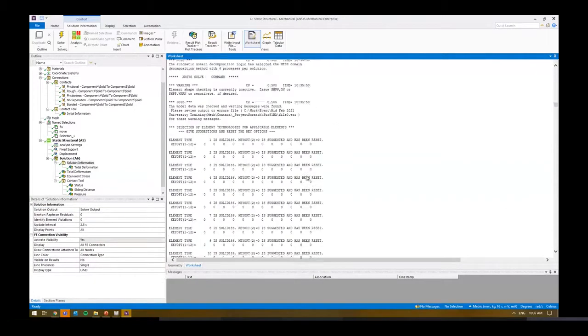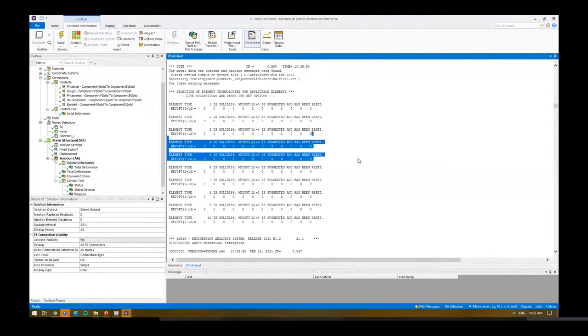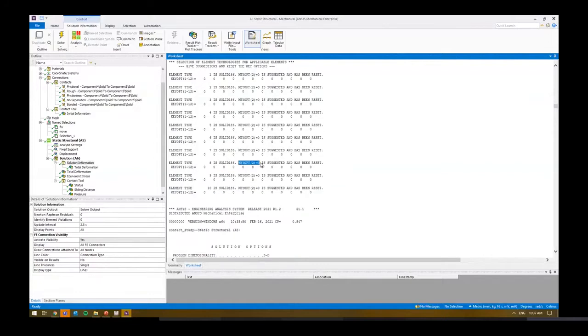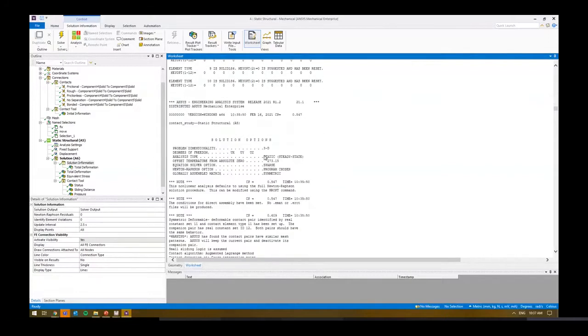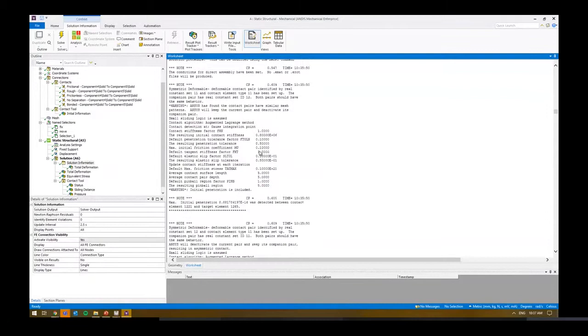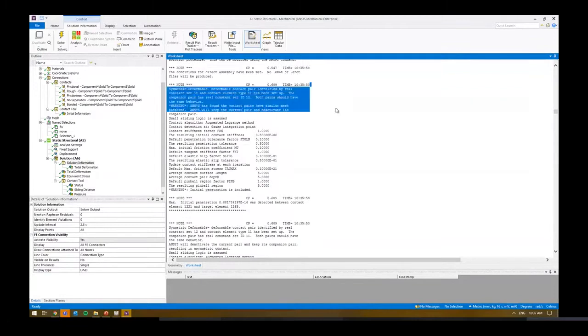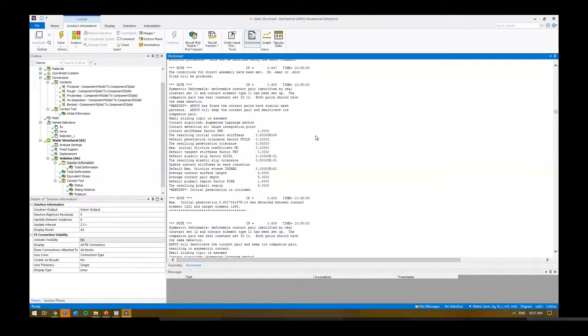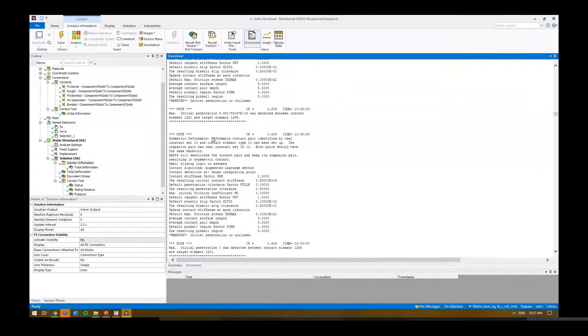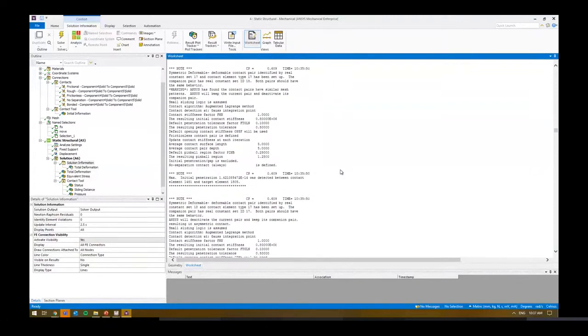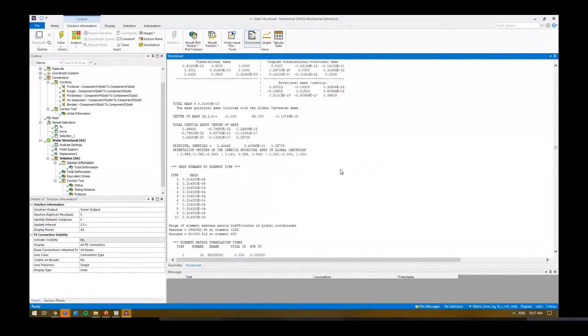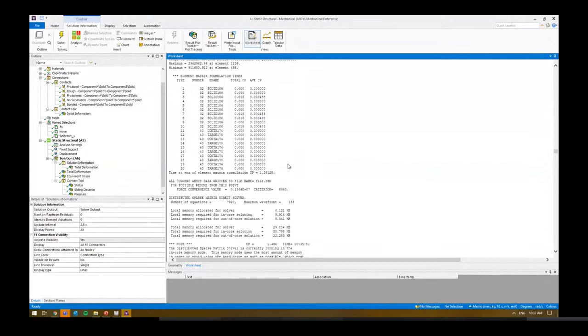So the solver output, you notice kind of what's happening. These key options are all about what's happening on the elements. So you can see here we're using what's called solid 185 elements, and these key options simply tell the solver how it is solving and what's happening in the background. We've got some information about some of the contacts that have been generated as well, right? So whether things are symmetrical or they're deforming. If we scroll down a little bit, you can see here we've got solid elements, we've got contact and target elements as well.